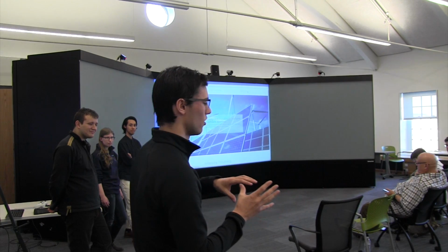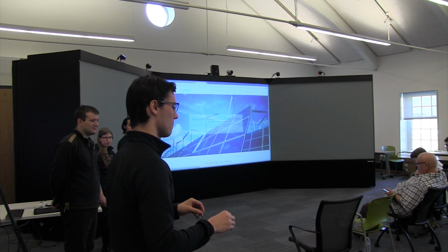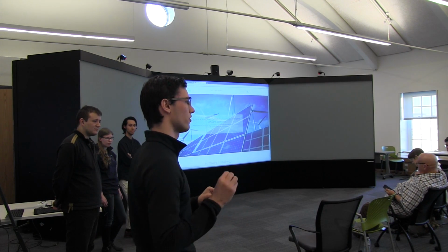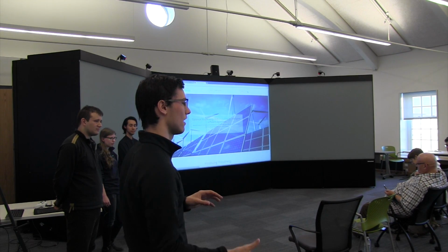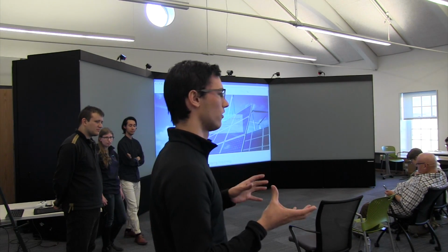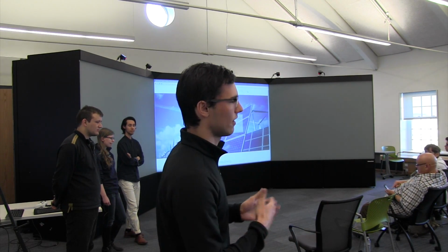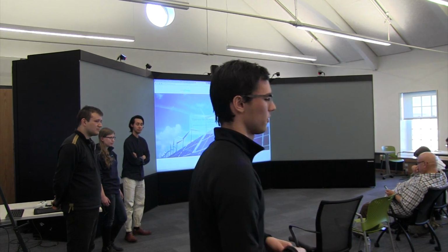If we have 110 volts at 60 hertz and it starts dropping below 59.5 hertz, they want you to supply energy onto the grid to stabilize that need until a big power plant can respond. With batteries, you're able to do that really quickly. The same goes if it rises to 60.5 hertz: you'd drain power from the grid.